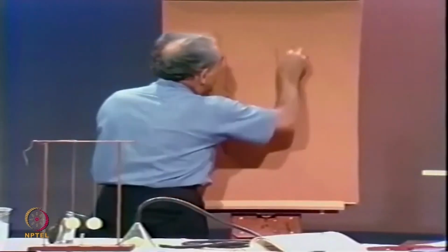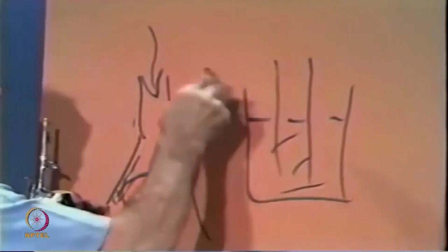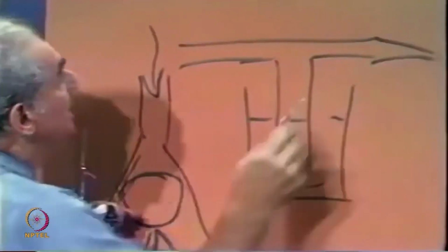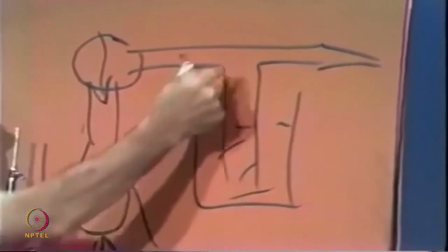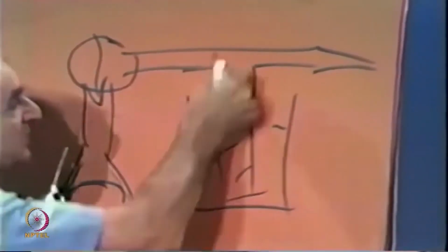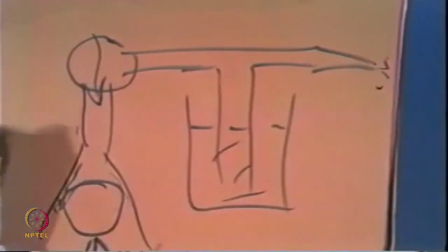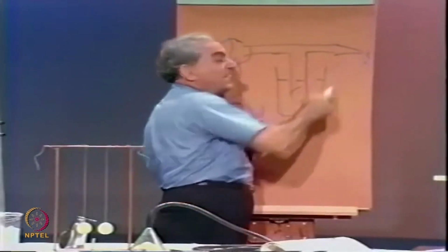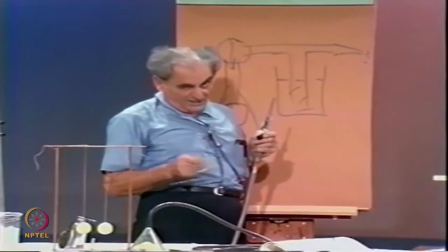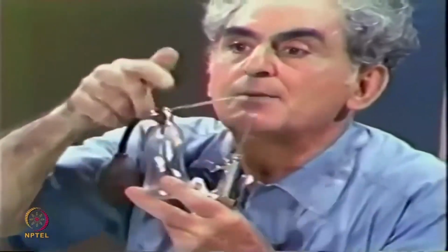An atomizer is a tube that resides in a vessel, and here is some liquid, and here is a tube across here, and here is a bulb, and you squeeze the bulb, air rushes across, there is a reduction in pressure, the atmosphere pushes the liquid up, and then the liquid is caught in the airstream and comes out there. I have often thought that the reason that's called an atomizer is because little atoms of the liquid come out there. Don't you like that idea, little atoms? Now, here is an atomizer, and spray would come out there.